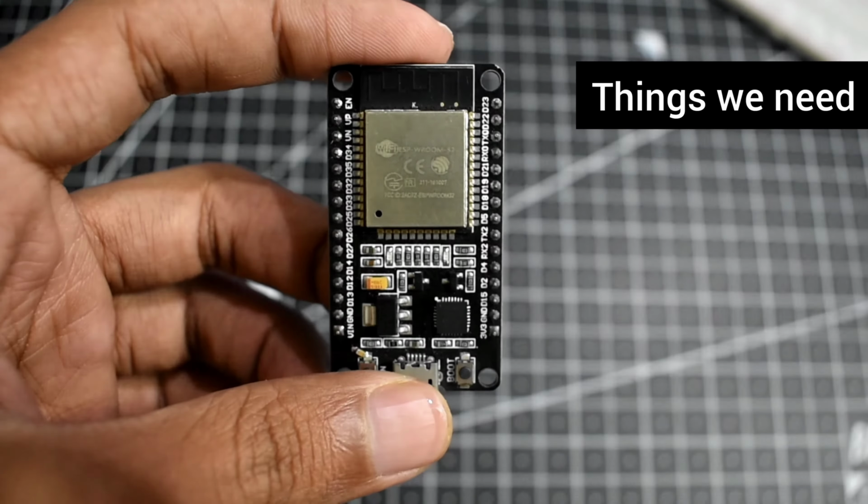You can change the frequency as per what you require. Since we want the data to be updated every 1 second, I have changed it to 1000. If you want it to change even faster, go ahead and change it down to 100. It's going to work. I don't need this part because it's serial prints. I don't need the parts that are going to be mentioned here.